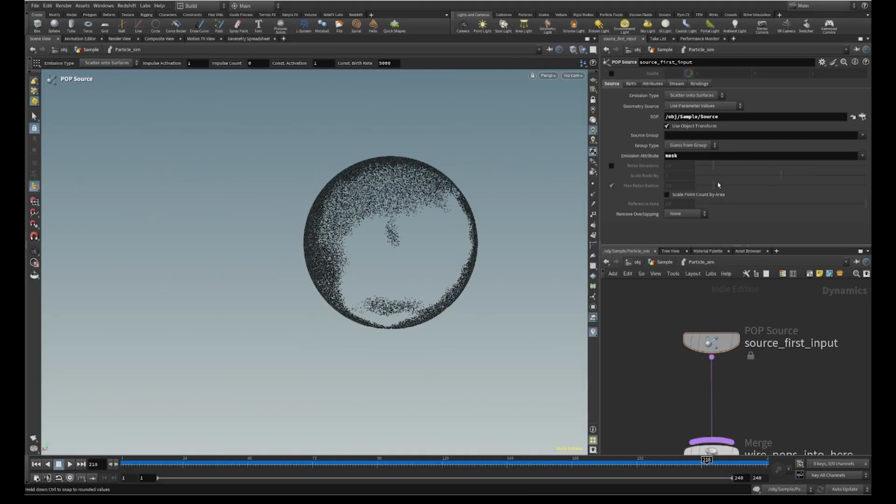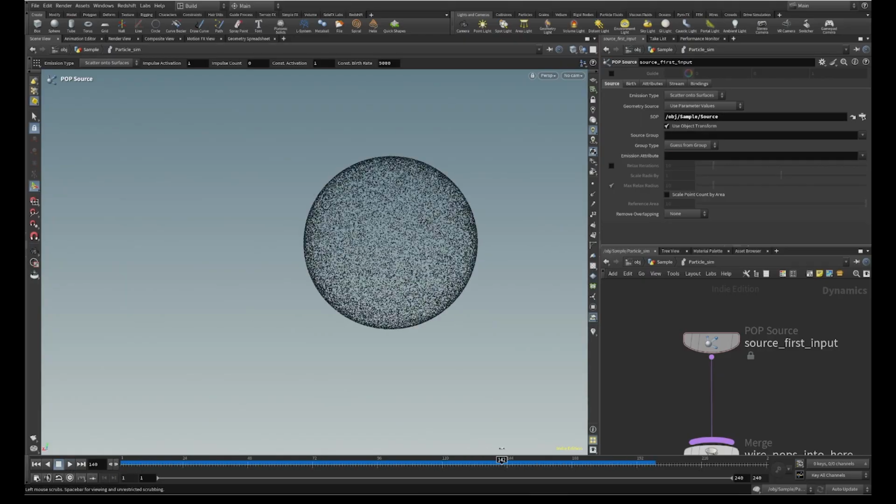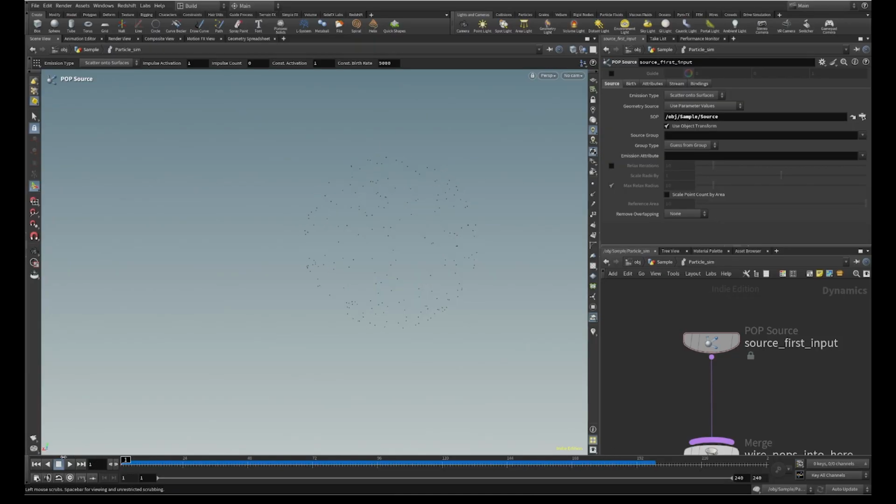Okay, so we've gotten here two very nice ways of controlling where we are generating our particles. One is emission. I think I always prefer to do it with emission, and in future tutorials you'll also learn this, that emission attribute is one of the better ways of controlling where the particles are going to be generated. I'll just delete this. Okay, I'll turn off the attribute representation, and you can see if I run this simulation, it is running pretty nicely.